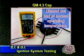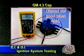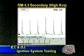Now, if you let that cap set for 10-15 minutes and let it cool off, the ohmmeter ohms that cap out as perfect. In other words, 0.3, 0.5 ohms. So we're basically telling you that when you took your scope and scoped that car under normal operating temperatures under dynamic conditions, then and only then would you have seen those excessively high firing kVs to alert you to a problem that's common to all the 6 cylinders.